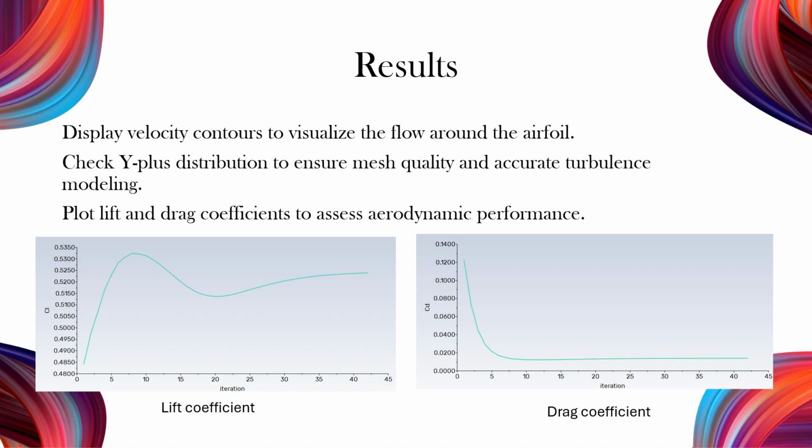After the simulation, we'll first display the velocity contour to visualize the flow regime around the airfoil. Next, we'll examine the Yplus distribution along the airfoil surface to verify mesh quality and near-wall resolution. A proper Yplus ensures accurate turbulence modeling and reliable lift and drag predictions. Finally, we'll generate plots of the lift and drag coefficients to evaluate the aerodynamic performance.